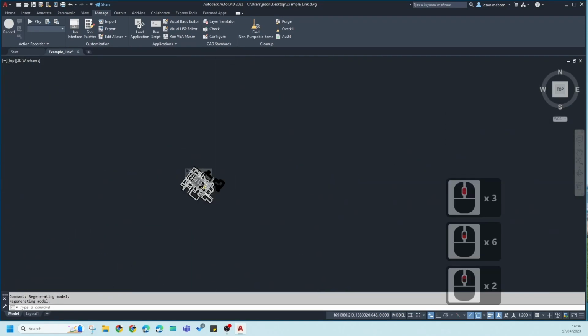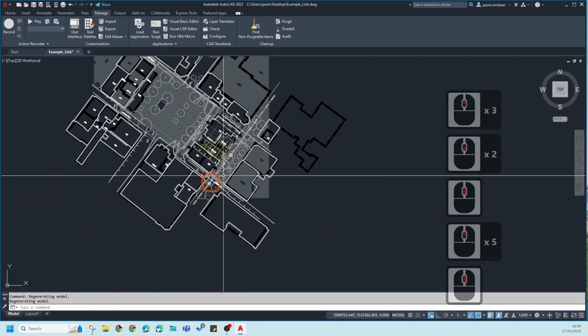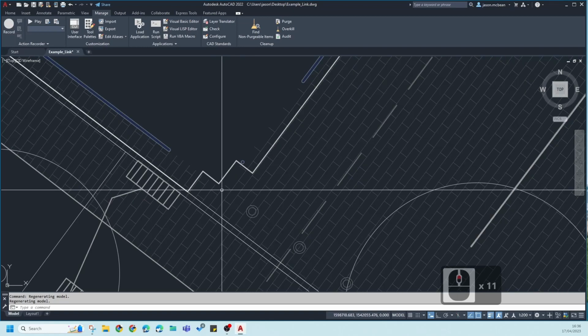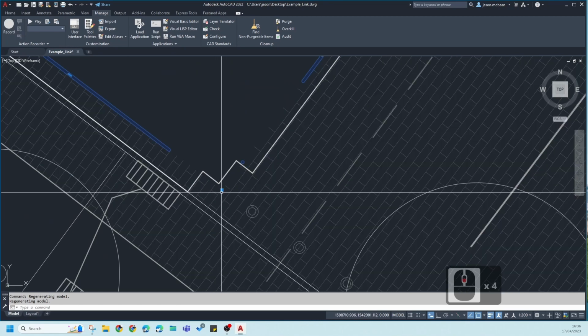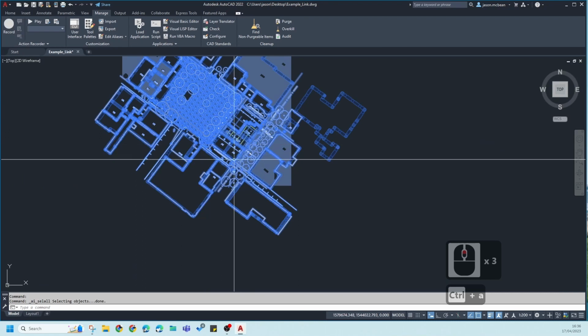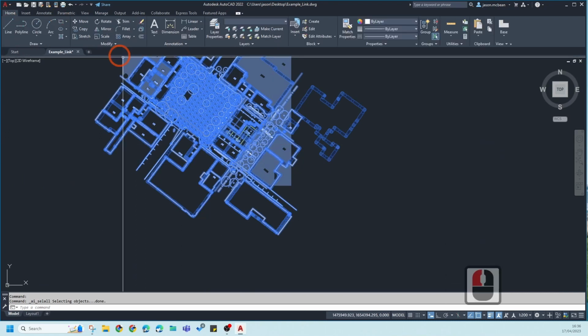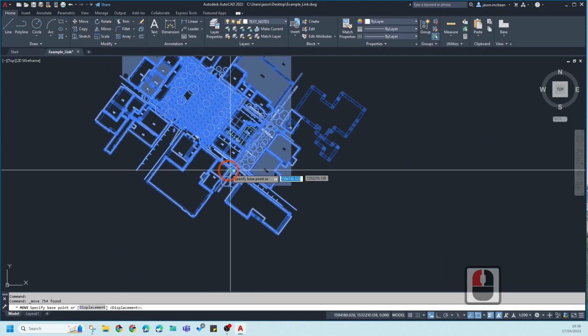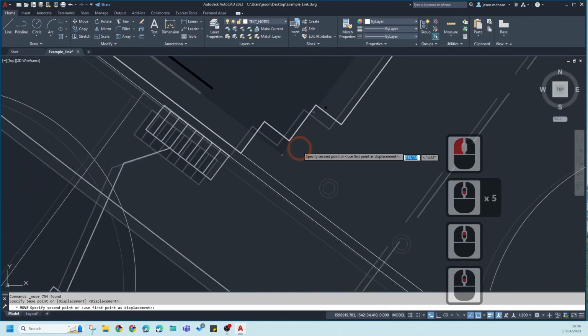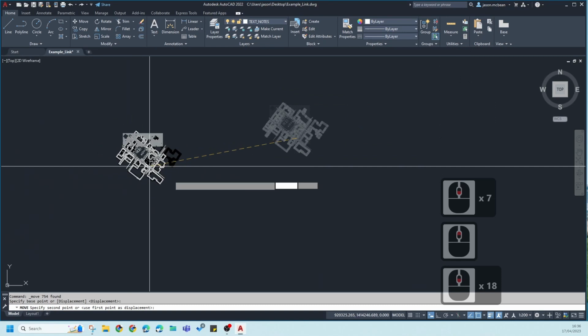The last thing I need to do is move, pick a point, and I think we must all use the same point. So we're going to use the corner of the cadastral information, so the site boundary lines. We're going to use this as our internal origin. So the last thing we do is you're going to press Ctrl A, select all the objects, go to Home, and we're going to use the Move function. And we're going to move this information from that corner to the origin.